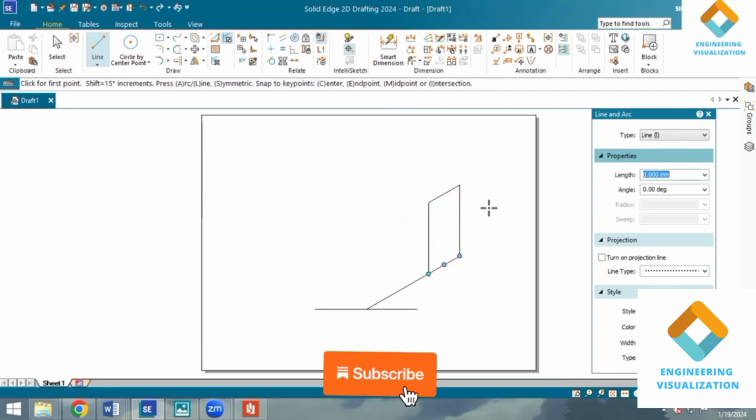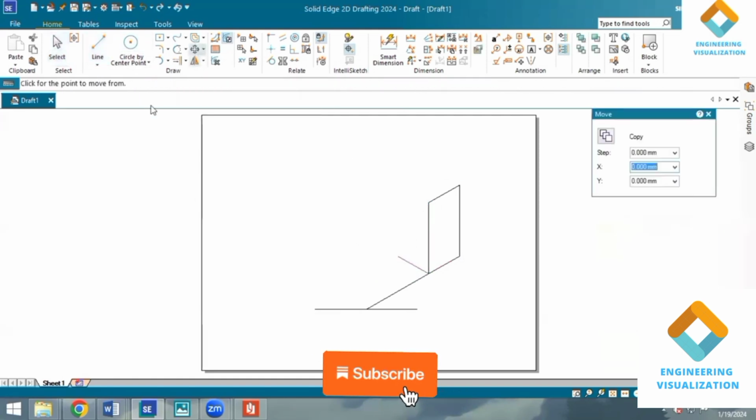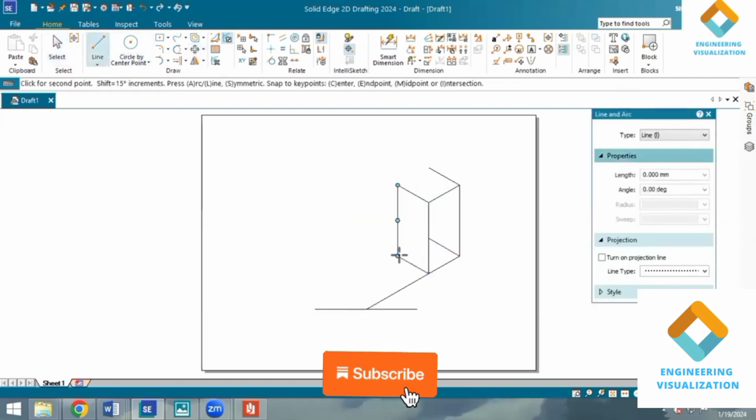Okay, now we have to give the width here. So width of 30 mm at an angle of 150 degree. Okay, so the same line I'm going to transfer using the move command, creates a copy, then place it like this, so it will reduce your effort. Okay, now complete it, so the rectangle block will be over.